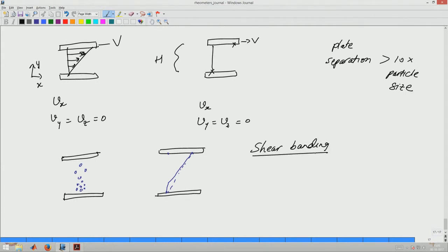where the flow breaks down into two domains. So, what we discussed was a case where we have two domains, one where the effective shear rate is low, while one where the effective shear rate is high. So, two regions, one low shear rate region and one high shear rate region. So, the flow has broken into two parts. That is why it is called a band. There are two bands which have appeared.